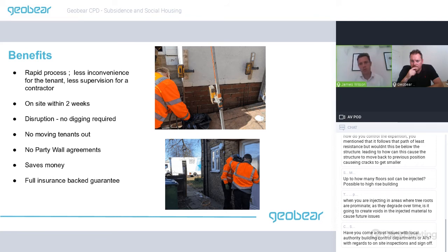So that's a really good question, Alfred. I probably could have put that in my presentation, because that's a really common use of the product. You can imagine the alternative: if you've got a floor slab that's subsiding, the alternative to drilling little holes and injecting resin underneath it is to break out that floor slab, dig out the soil that's been compromised for whatever reason, replace it with some other aggregate, and then relay a floor slab. That's hugely disruptive to someone. That's definitely move out for a couple of weeks and come back. So it's a massive advantage for people like that.